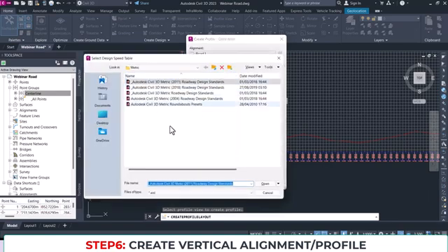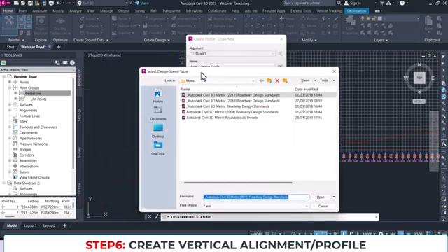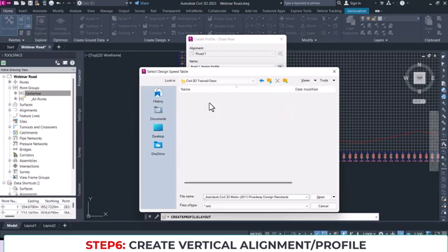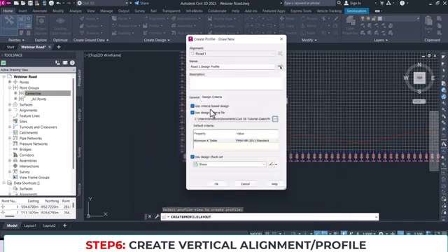If I wish, I would have just saved that design code here, so that Civil3D always sends you to a particular folder by default. So if I bring my code here, next time I don't have to start browsing through to find where I've kept it. That's the importance. So let me uncheck this and press OK.